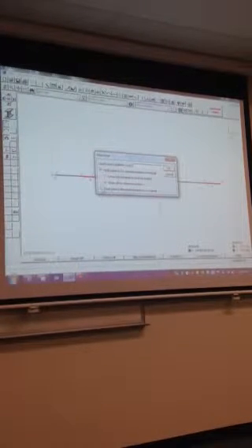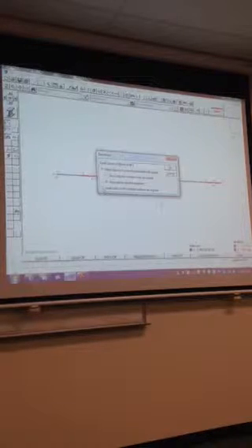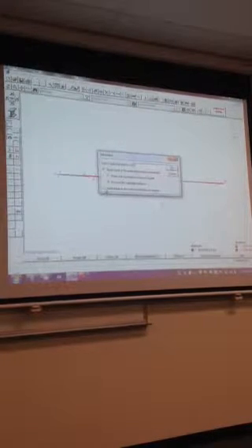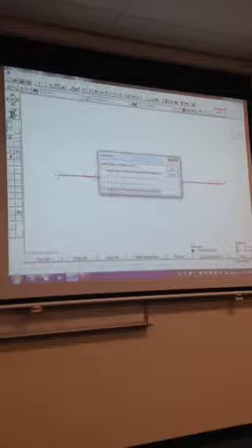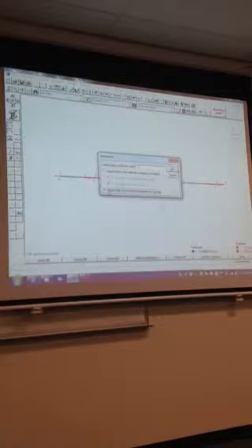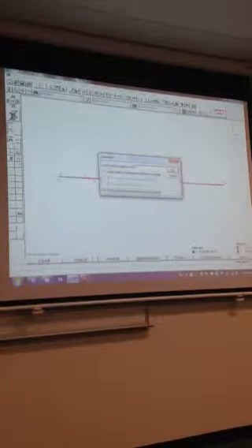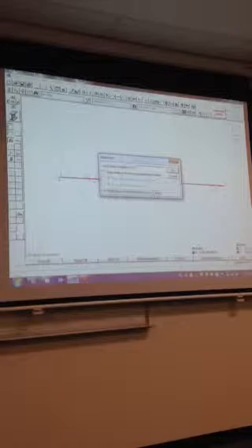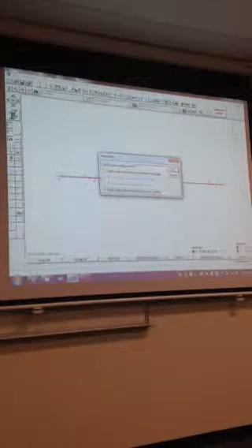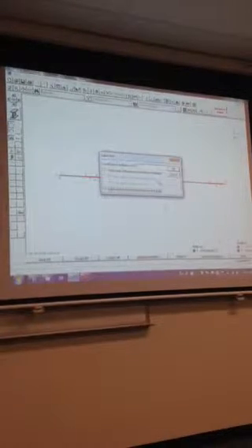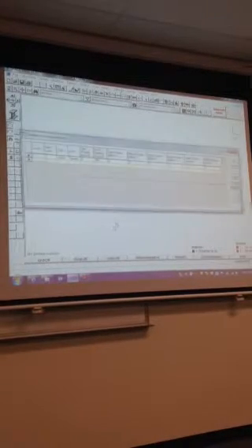Importantly at this stage, since you've selected all the members, I only want to input one load. So we're going to click the dot down the bottom that says apply loads to selected members as a group. If you selected a whole lot of random members and wanted to have the same load on them, that's what you would select. Now it gives me one input screen here.